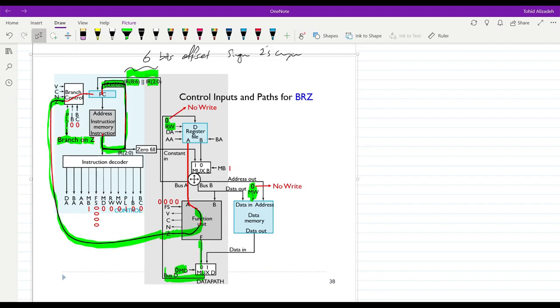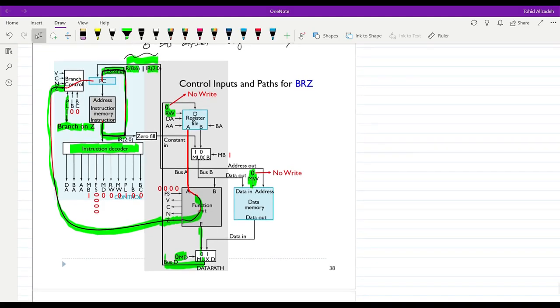So you can see that by providing the OP code and using the instruction decoder, the proper values for the control signals would be generated, and then they will determine for the data path how to function, yeah? How to create the path for the data, and then which operations to perform and where to store the result of the operation.